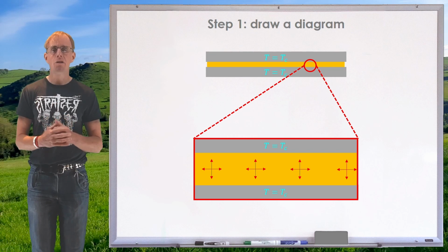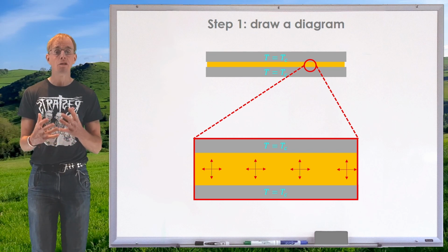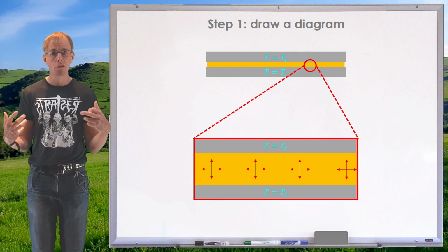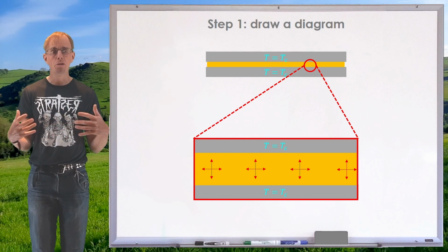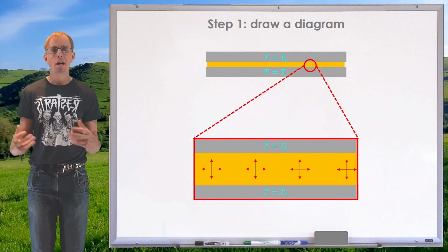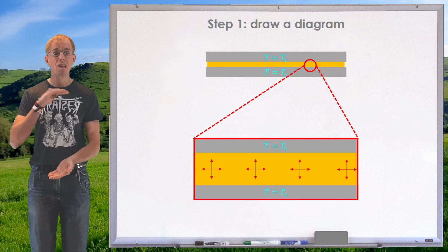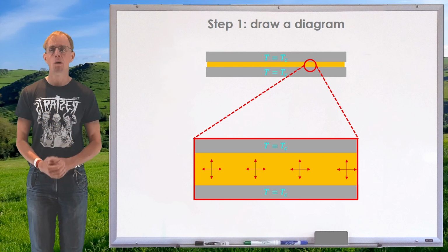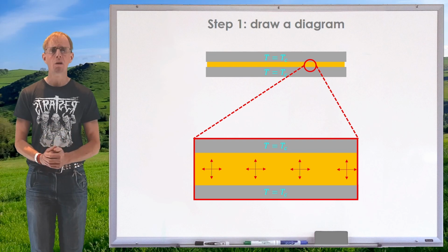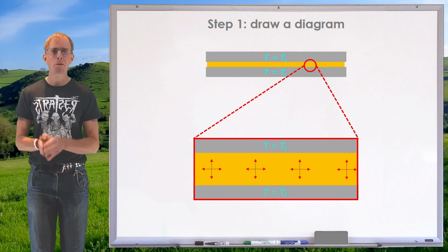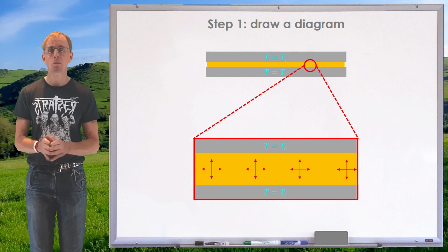So imagine that what we've got is a mould with cooling channels built into it. We've got the mould nice and hot to accept the molten polymer coming in, and then we flood those channels with coolant, and we achieve a near step change in mould temperature. It doesn't really work that quickly, but for the purposes of this example, we're going to assume that it does.